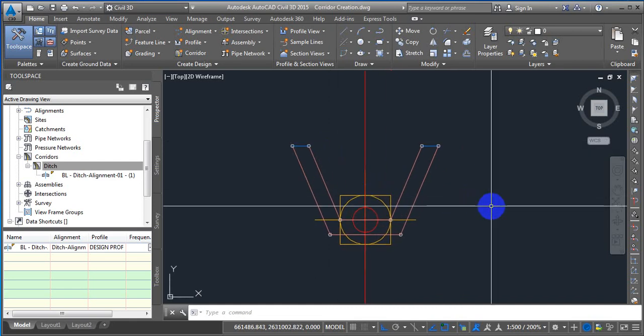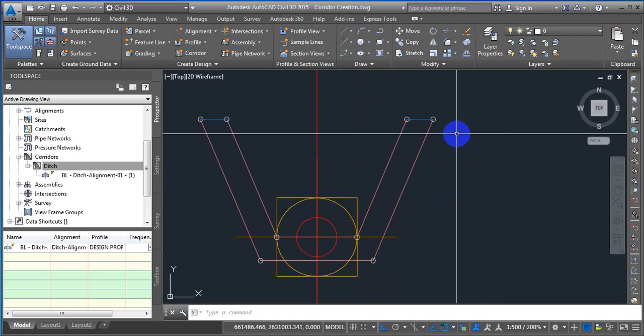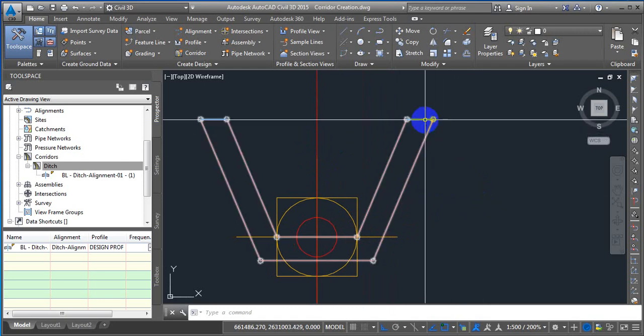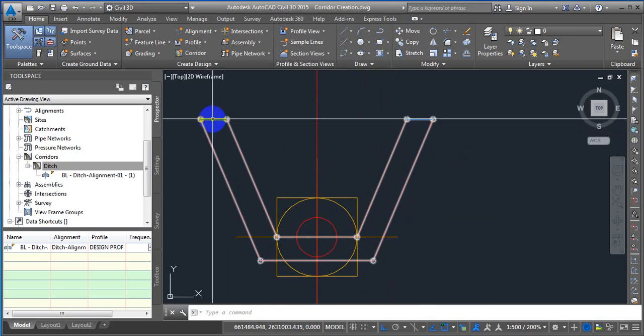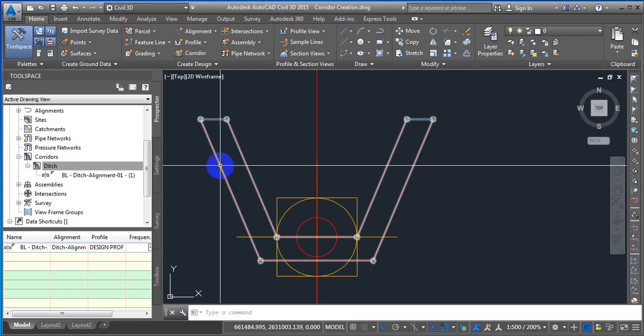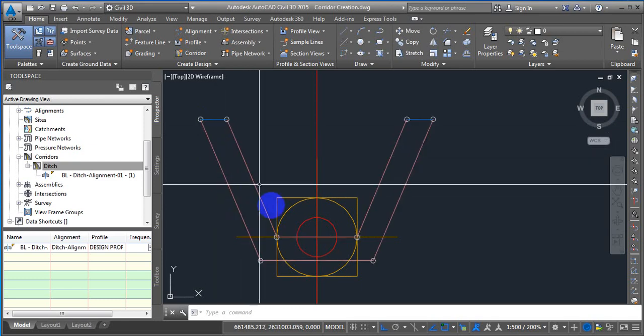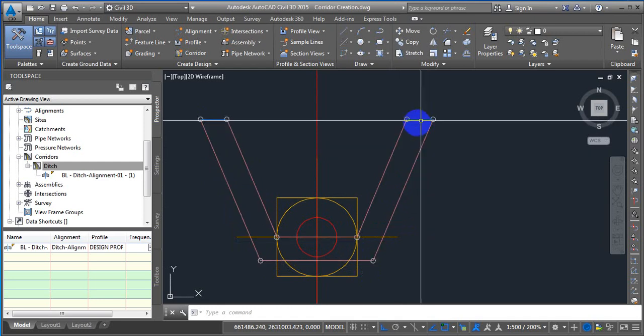Interesting thing is that if you come to the assembly and just hover, I mean you just take your cursor to the link, it will show something. It shows link codes top of wall, and if you go to the other one, it also says link codes top of wall. But if you go to the other links, it says link codes uncoded. So codes have not been provided to these links. Okay, we only have provided links to the top links.